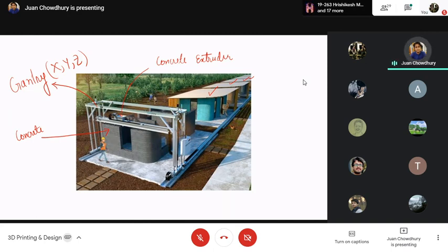One drawback is that you need a really flat rail for this gantry system to move about. Any undulation in the system leads to an uneven structure, which again is a promising field: how do you make this structure actively leveled, by using some spring-mass-damper system to actively stabilize it, so it does not matter if you are on uneven ground, it will stay level and the 3D printing process will carry out. So if you someday come up with a company which can do that, amazing, you'll be a millionaire in no time.